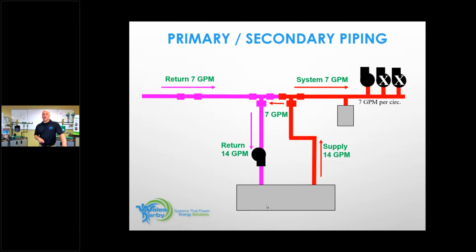Who can tell me how that condensing modulating boiler will react right now based upon 7 gallons of partially heated water, used some of it through the baseboard, combining right there, and then going 14 gallons into the boiler? How's that condensing modulating boiler going to react?